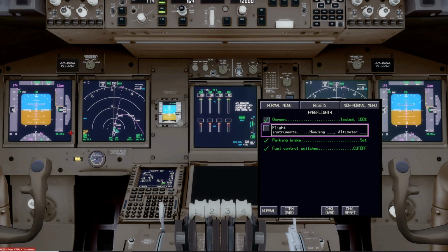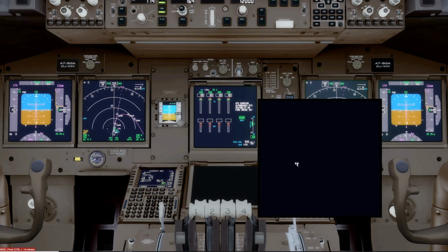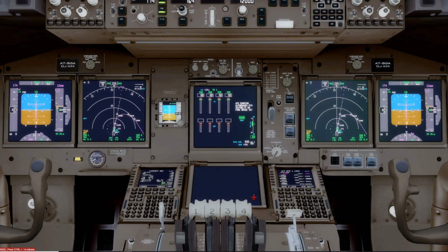We're checking the heading in 5 places. We're checking it here, here, the mag compass, here, and here. So 5 different places we're checking it, but we're only saying it once. Check that off, and pre-flight checklist complete. Then we stow the checklist. And then we get the ATIS, get the clearance, set up the clearance, and then brief.